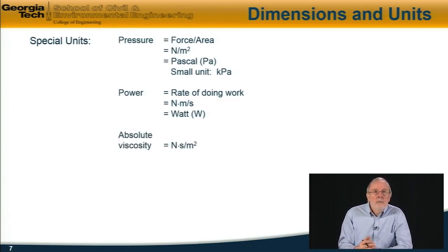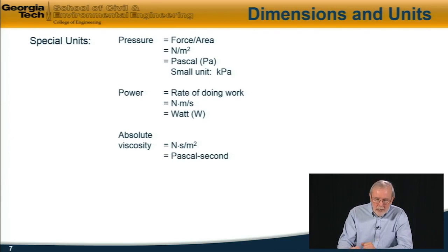Another one that comes up sometimes in fluid mechanics that we'll encounter is absolute viscosity. The units of viscosity in metric units are Newton seconds per square meter, but you will sometimes see this given as a Pascal second, abbreviated like this.